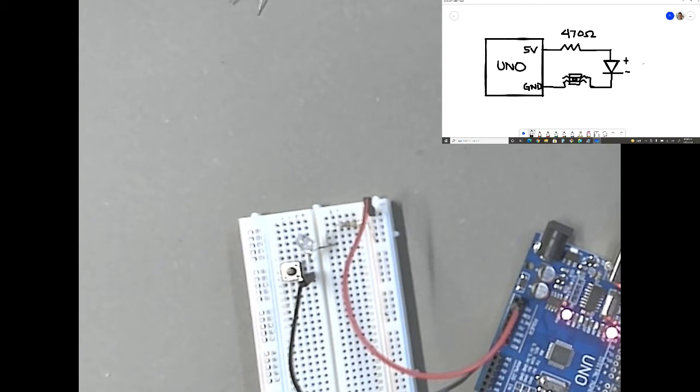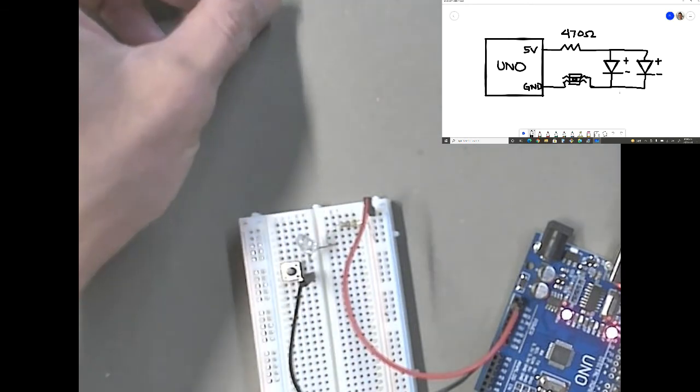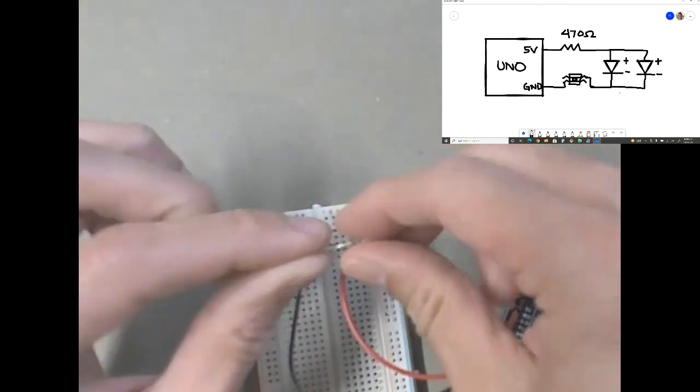So you take the second light, so I'm going to draw it, and you connect it to the same connections as the first light. So there's plus and minus. We take plus and connect it to the plus of the first light. We take the minus and connect it to the minus of the first light. That's all we do. So let's get our other light here.